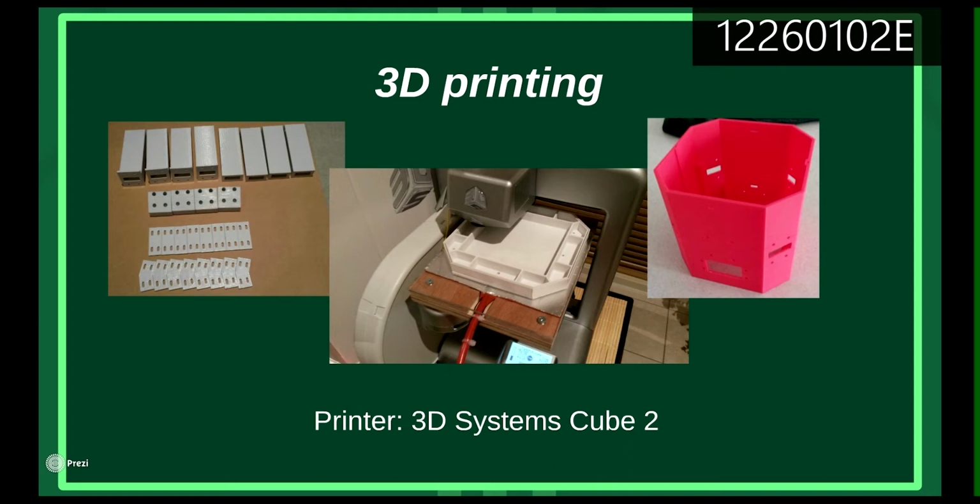There were two major challenges with this technology. First of all, I had to learn how to use CAD software from scratch. I always had to take into account the nature of 3D printing, for instance, avoiding overhanging parts which require messy support material to print. Secondly, I was working at the printer's limits due to the large parts I had to create. To ensure good quality prints, I had to re-engineer the print bed to ensure the plastic parts did not warp as they cooled.